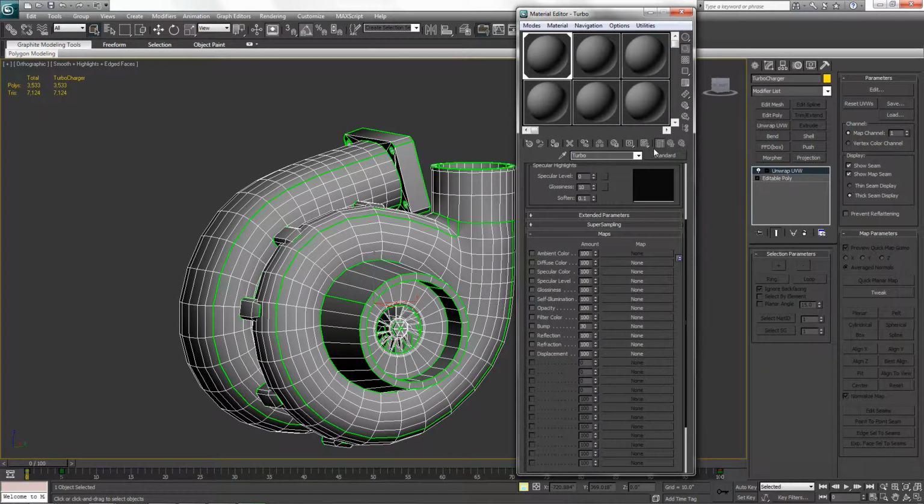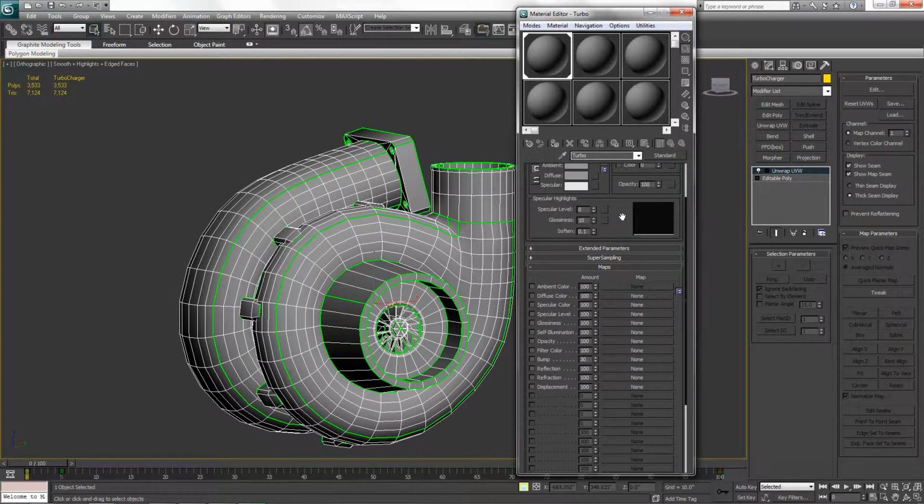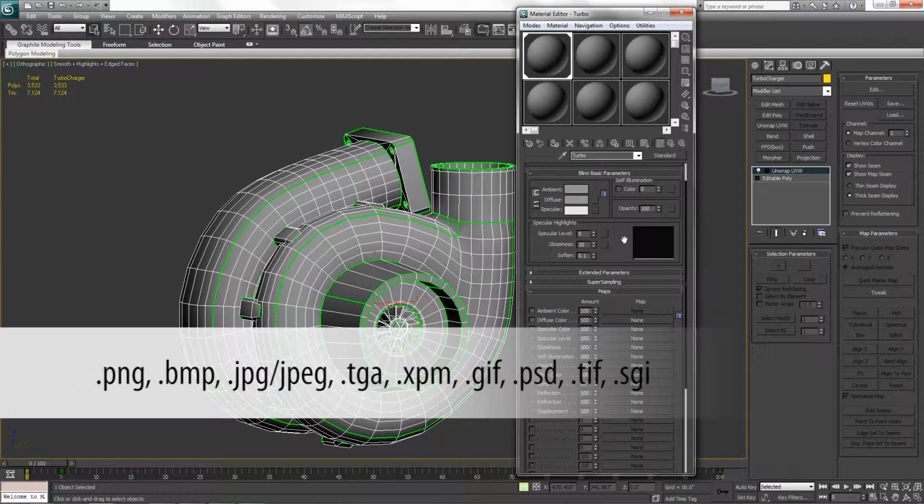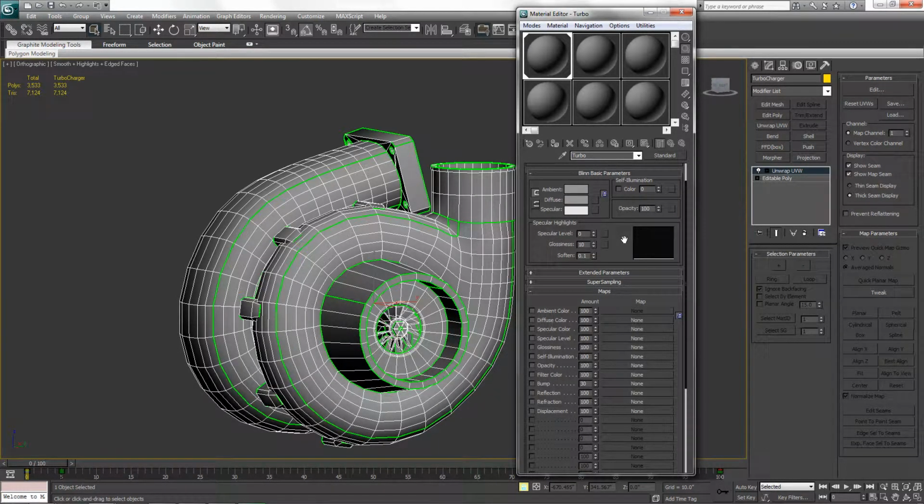We'll go ahead and open up the material editor here. Each individual texture map that you'll be creating can be saved in any number of formats. We'll go ahead and display the full supported list on screen here. And we'll generally use PNGs here at Disti and within this tutorial, mainly because they have lossless quality and an integrated alpha channel. One other restriction is that your final textures for output to the Replicate editor should be a power of 2 resolution.